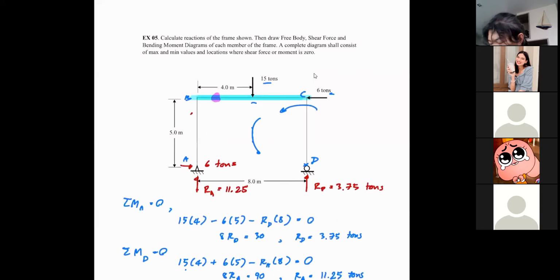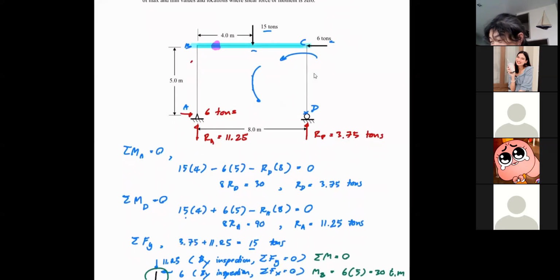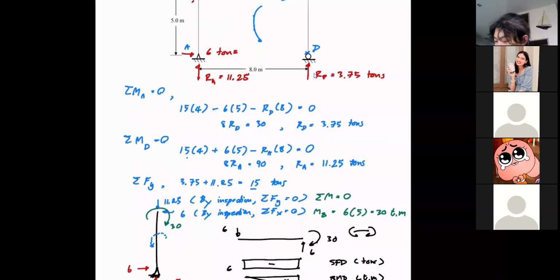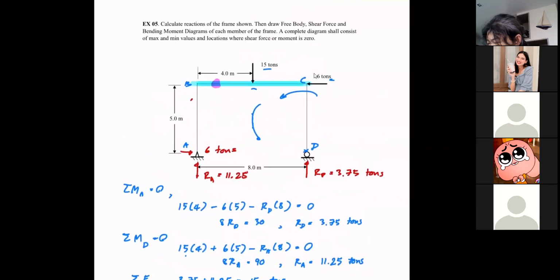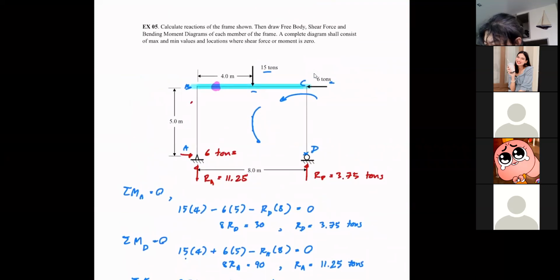More challenging, this one. Now, you see, that is your bending moment diagram here, right? Compression on this side. But again, because the frame is being pushed from right to left, let's use the screen, make it bigger. Your frame is going to move like this. Again, compression is on the side of your bending moment diagram.